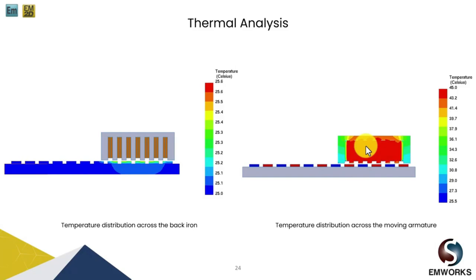coils. Therefore, using this thermal analysis, a user can understand how much heat dissipation is required from the motor, either by designing a better airflow path or incorporating circulating liquid jackets in the motor core. So that helps you to analyze so that you can control the heat generation and the temperature of your machine.